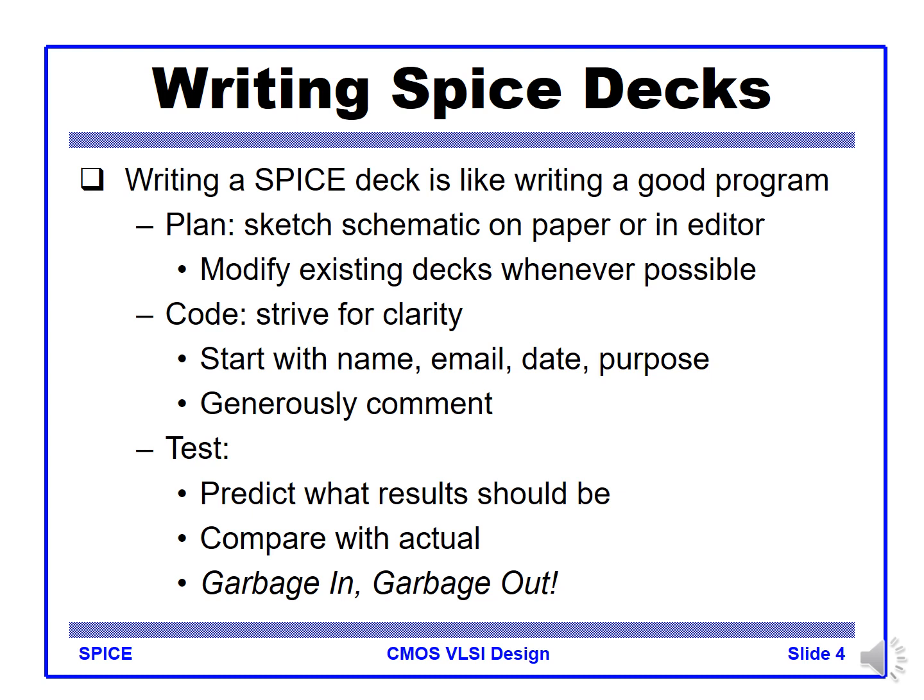This is about how you write the SPICE deck, and it is like writing a program. First you have to plan and sketch. This is the planning stage, then the actual coding stage and the testing stage. So first you sketch the schematic on paper or in an editor using a GUI.